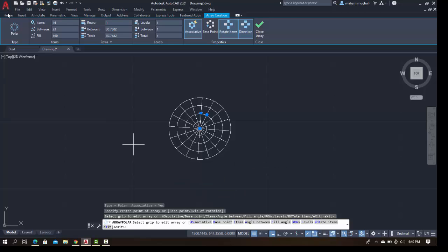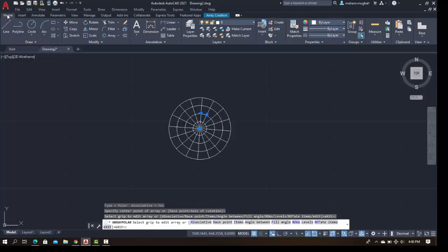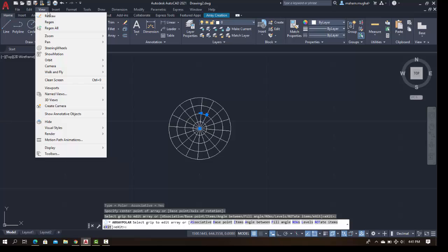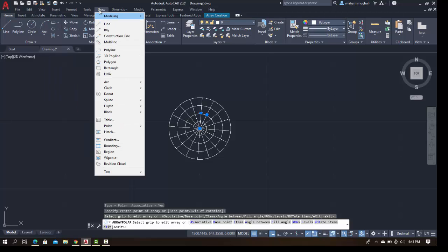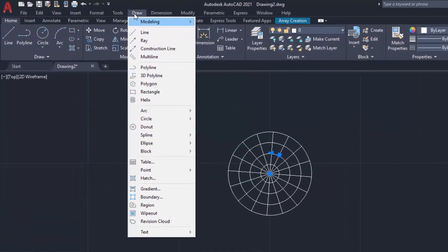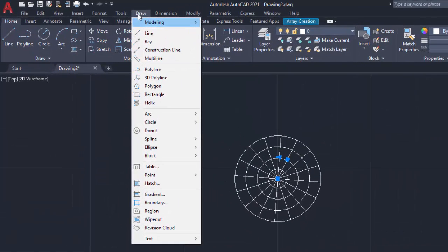Now let's go back and do something interesting today. For that, we want to color the parts that the real gray code wheel has. So we'll learn coloration today, and for that, I want you to open up your draw panel from the very topmost bar of your screens, the one that has file, edit, insert, format, tools, draw, dimension, modify, parametric.